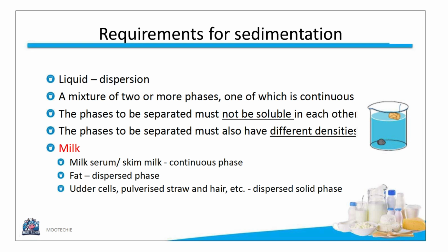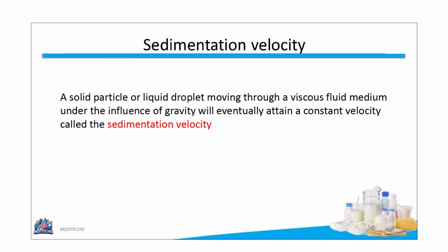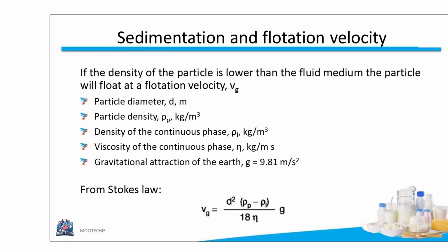A key concept is sedimentation velocity. A solid particle or liquid droplet moving through a viscous fluid medium under the influence of gravity will eventually attain a constant velocity. This is called the sedimentation velocity. We can calculate sedimentation and flotation velocity using Stokes' law.